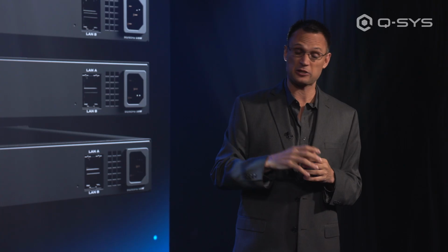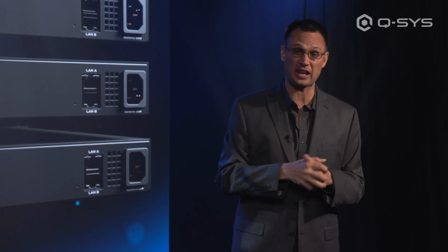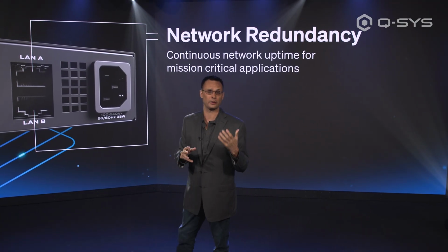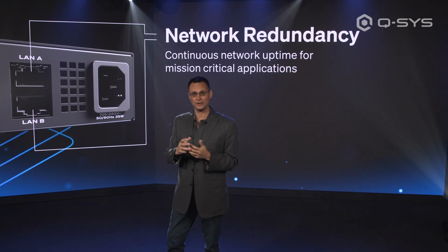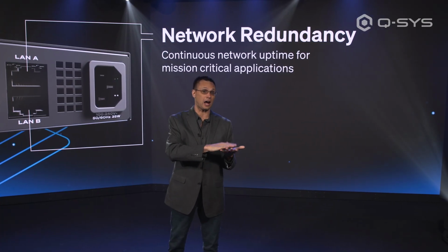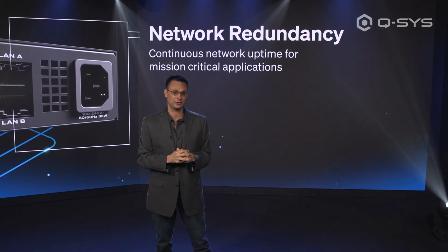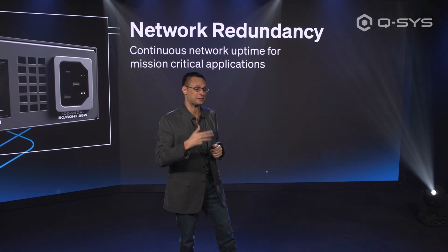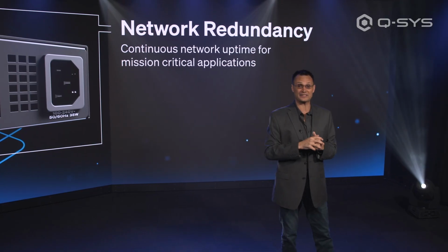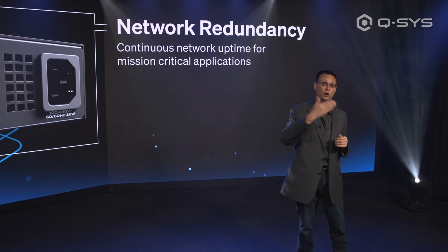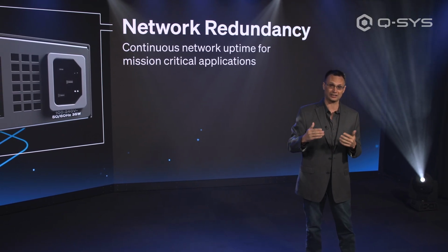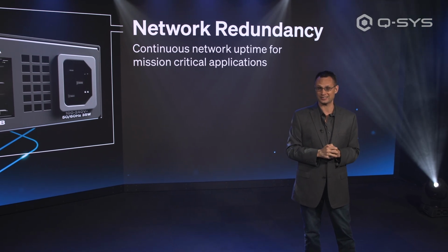And because this is probably going to live in the rack, it's going to be powered not by PoE, but with a standard power cable. And that actually allows us to do some redundancy options that we weren't doing with the other QIO devices. So we now have the ability, much like any other network device that is operating in redundant mode, these QIO devices operate in redundancy mode as well. So if you have all of your inputs going into the first device, and that device suffers any sort of failure, it detects that there's a fault of some kind, it needs to swap over to the redundant device. That'll be a very, very short changeover as the secondary device comes online and the primary passes everything over to that secondary one.